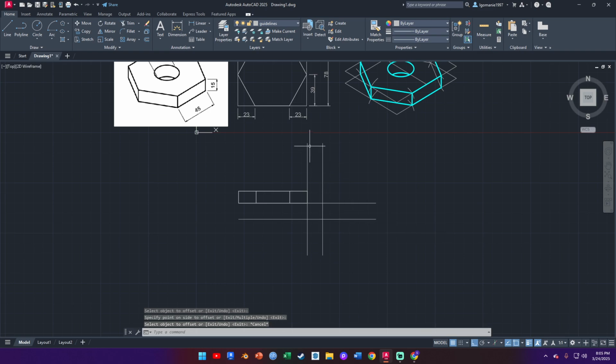So now you have your 20 mm space in there, and now we can draw the other views. So this space directly at the bottom here is going to be used for the plan view, because the plan view is found below the front view. Remember, this is first angle orthographic projection, right? And the space on the right hand side here is going to be used for your end view, seeing that the end view is on the right hand side of the front view.